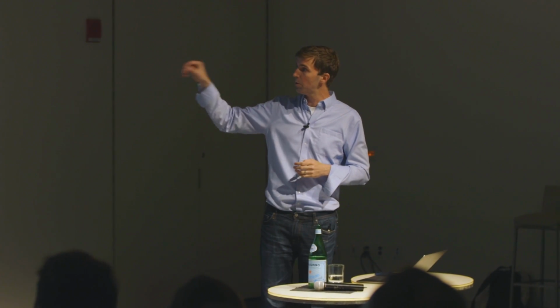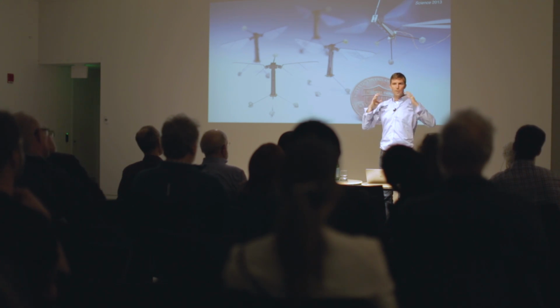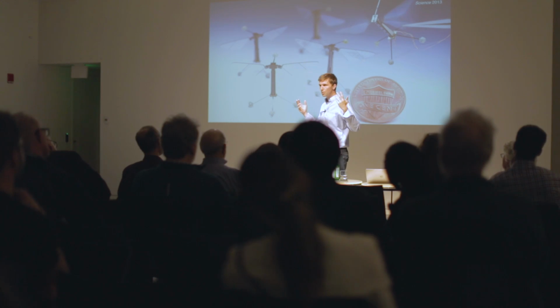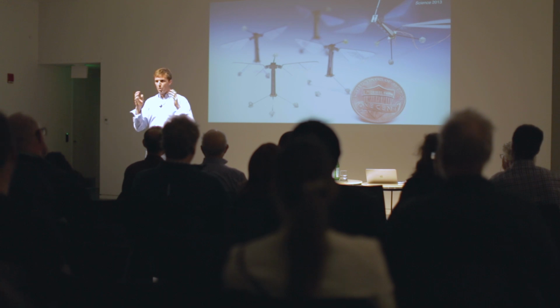And this is a very simple device. The way that it works is I cut the robot down the middle, and I have an actuator on either side, and that actuator is basically just a little artificial muscle that's doing this. And that very small motion is then mapped through a flexure-based transmission mechanism. It's just a gearbox without the gears, because those wouldn't work, and I'd be happy to tell you that offline. And then that little motion gets amplified into this large flapping motion.